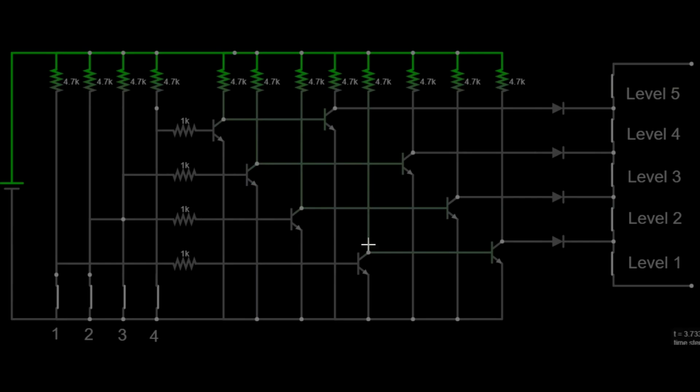The circuit shown here represents the floor selector, the navigation part of it. These contacts represent each floor, and if an elevator is sitting at a particular floor, the contact for that floor will be open. These are the call switches, which would go to the SR flip-flop circuits that are used for the call buttons. And then any of these inputs going high will tell it that the lift needs to go to a particular floor.